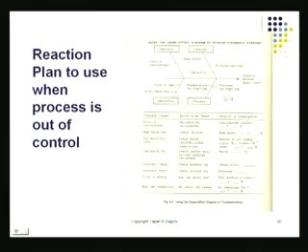What you do is, you sit with people, those who are actually familiar with the process, and you construct, look at the top half of the page here. You recognize this tool here, this is your simple fishbone. And the fishbone says there are certain conditions that will drive your process beyond specification limit. And many times these are the factors that also make the control charts go beyond control limits or show some exceptional patterns and so on. Now say you have found a point beyond control limits. Stop the process.